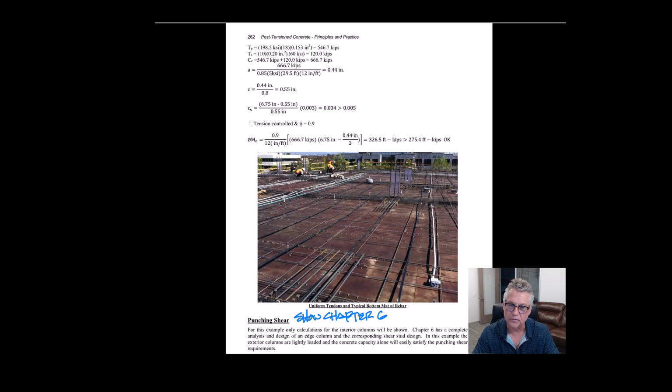Not unusual. In fact, this slab is highly usual. It's typical. These spans of 30 feet are very typical in a two-way flat plate slab. 40 pounds a square foot, that is your parking loading. We threw in 3, for fun, but your apartment loading is 40 pounds a square foot. Condominiums, you're not going to be typically much higher than that. So this design is normal. You'll see this same thing happening in your designs.